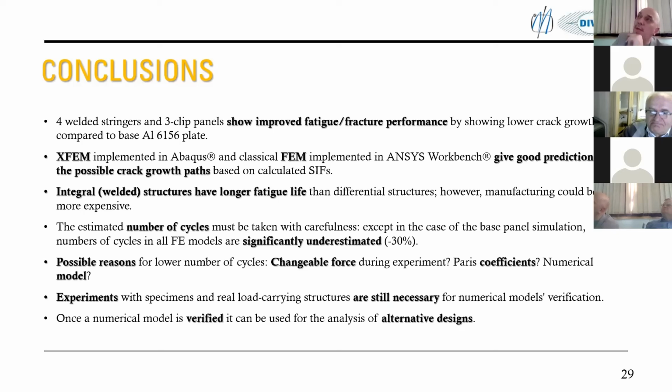Also, we can conclude that both XFEM and FEM give good predictions of the possible crack growth paths in a structure. Definitely, welded structures, and talking about aluminum welded structures, have longer fatigue life than differential structures. So even if we compare just welded with differential, we saw that in the experimental investigation, the number of cycles was longer, and this is the problem that we are still working on.